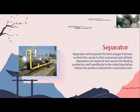In these condensate tanks, because of the difference in density, the lighter fraction of gas will gather on the top of the tank, while the heavier gas condensate will be in the middle of the tank, and lastly, the water will accumulate at the bottom of the tank. The lighter C1 and C2 fractions of the gas will be transferred to other facilities after separation.